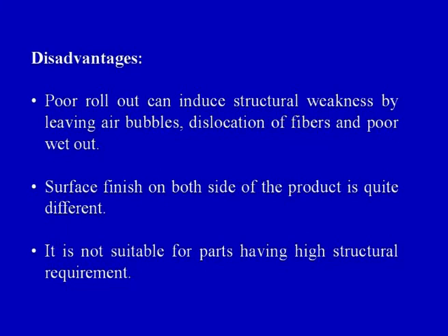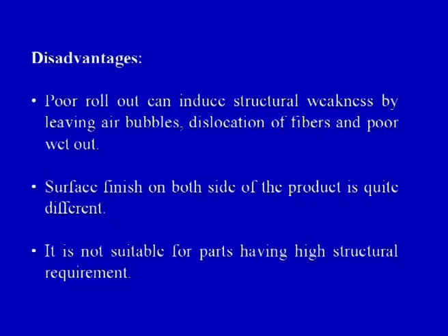What are the disadvantages? Poor rollout can induce structural weaknesses by leaving air bubbles, dislocations of fibers and poor wet out. So sometimes the fiber may not get properly wet out, there may be dislocations of the fibers coming out of the matrix, and sometimes there may be air bubbles inside if the consolidation process has not been done properly. So all these factors will lead to poor mechanical properties of the part which has been made by the spray layup process.